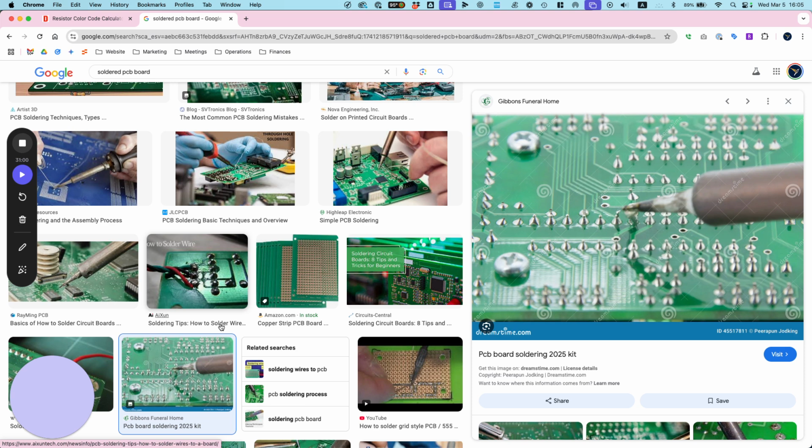2.2. Right there. Yeah, that's ideal. Yeah, exactly. It should be 2.2 across each of these. Okay, well, I wanted this to be a higher number. Let me throw this up to a higher number. Okay, I'm just going to throw it to 5 volts, even though it's really bright now. I don't want to burn out the LEDs.